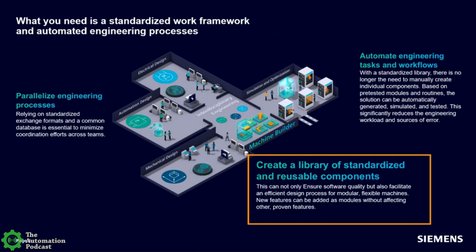And as you mentioned, one of the keys to efficient engineering is standardized reusable library components, library objects. I've been doing it for my entire career, providing a reference of what we want you to do when you implement a PLC block, an HMI screen, a drive configuration, basically ensuring that there's reusable known code that gets applied over and over again that provides the best path forward for machine design, using something that we know works. Fits in that whole concept of efficient, reliable engineering.